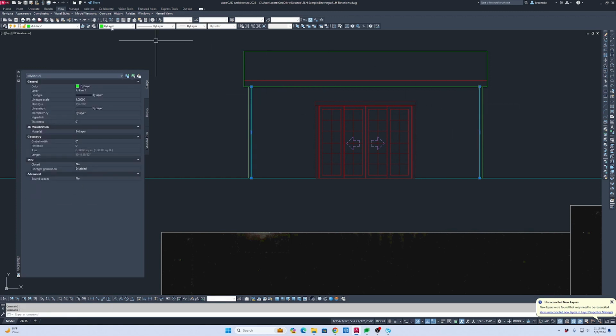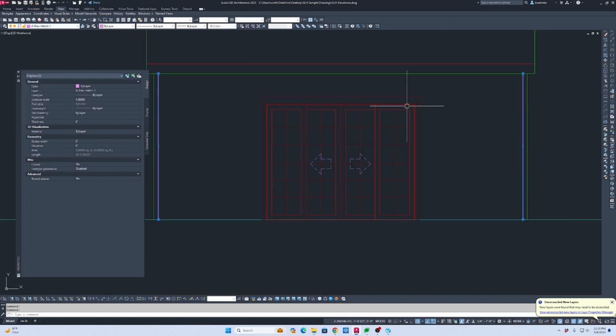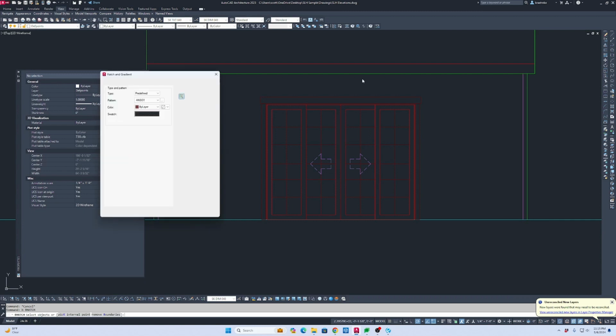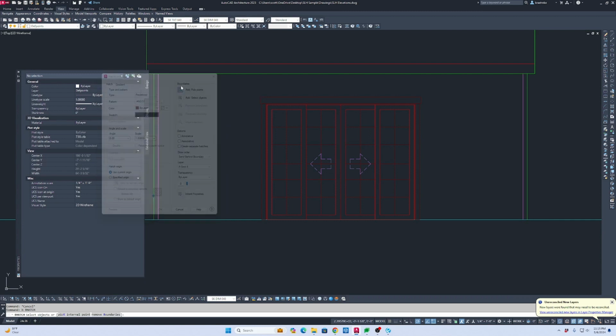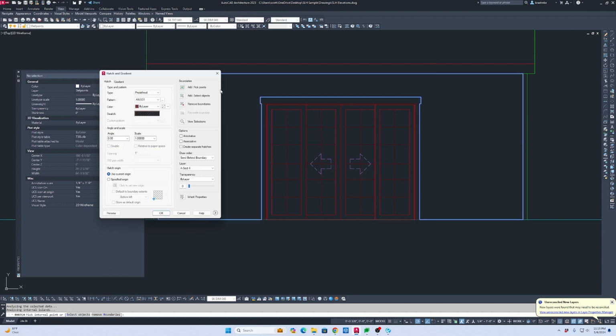And so these I'm going to do on hatches. So elevation hatch, let's call it elevation hatch 1, and let's just fill her up. We're going to hatch this area, pick a point, that point. We're going to do a line hatch, and angle is 0. Scale, if we're doing 6-inch, it's going to be 48.